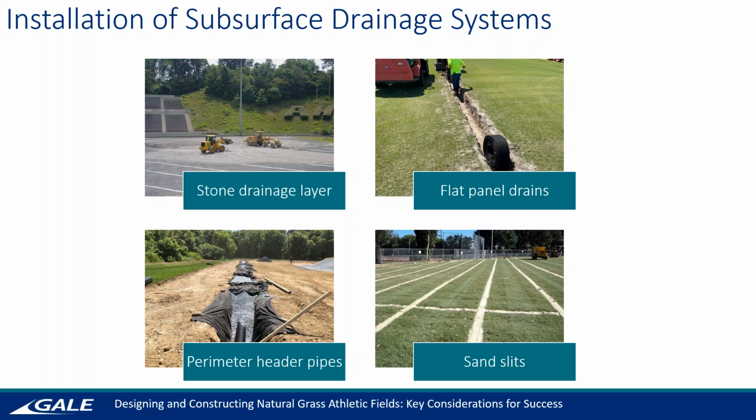These are laid down either flat and then top dressed with sand and then sodded, or you can use them vertically, which is an even more minimal disturbance. We're talking 4 to 6 inch disturbance. A small trench digger like a Ditch Witch could do it, and then you would drop these in vertically and top dress with sand.